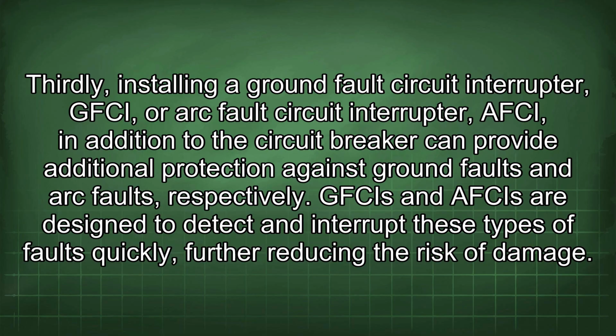Thirdly, installing a ground fault circuit interrupter, GFCI, or arc fault circuit interrupter, AFCI, in addition to the circuit breaker, can provide additional protection against ground faults and arc faults, respectively. GFCIs and AFCIs are designed to detect and interrupt these types of faults quickly, further reducing the risk of damage.